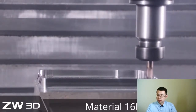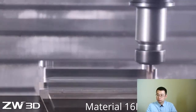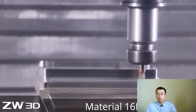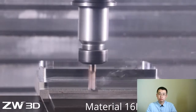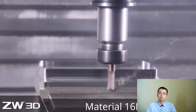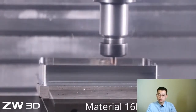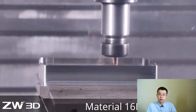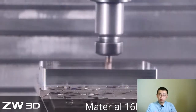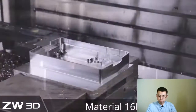Now we can check the corner area, where it will move the tool in smart passes to avoid clashing with the material. Again, if you focus on the chips that are removed from the material, you will find that almost every one of them is of equal size. We have a picture to show the size of the chips. You can check it yourself. Almost the same size, because volume mill will drive the tool under a balanced load at all times.